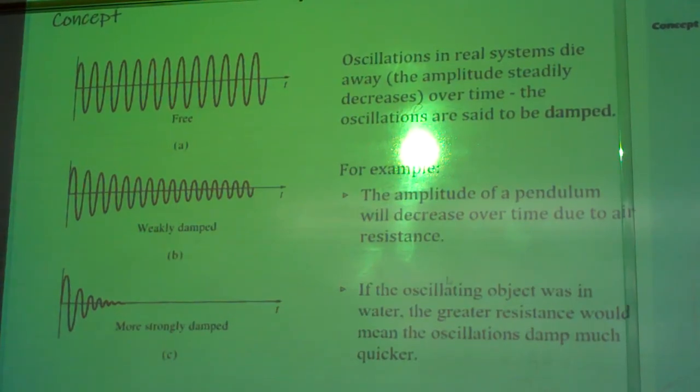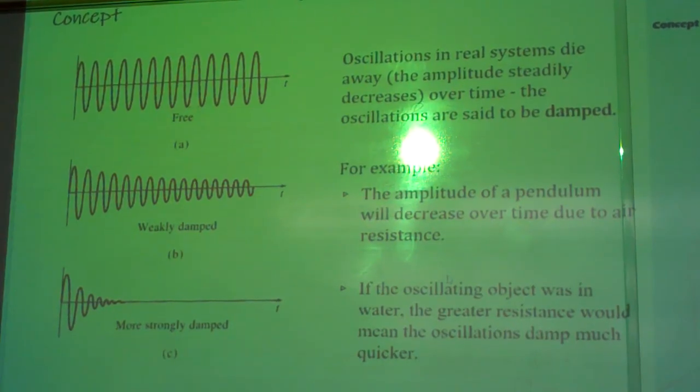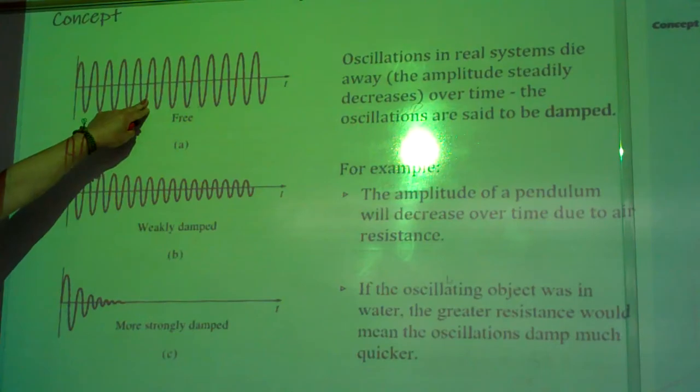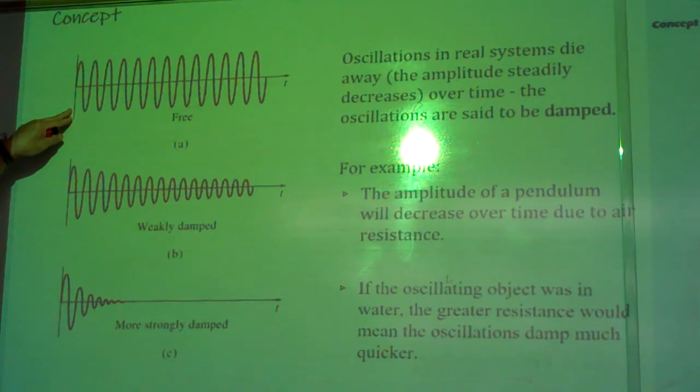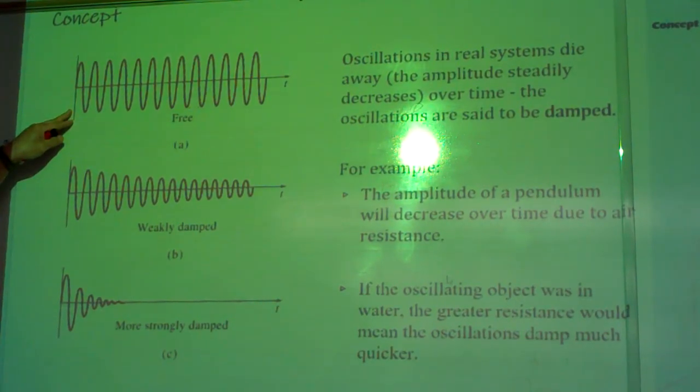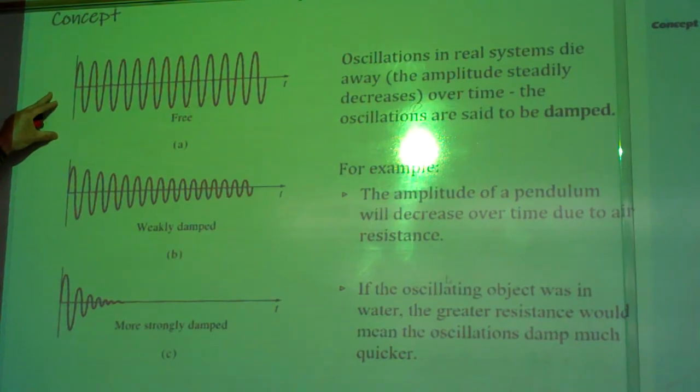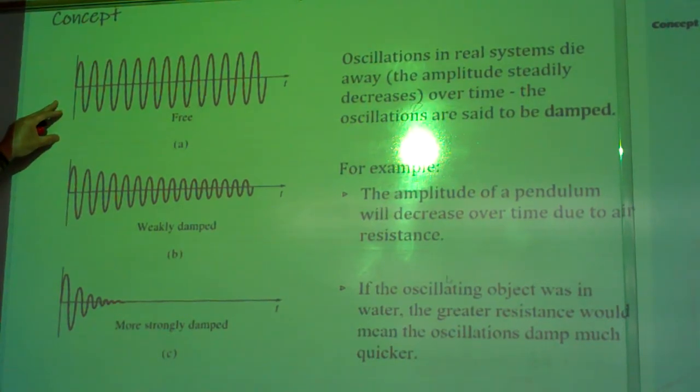Basically, here I'm showing you that if we solve for the system vibrations and plot them, the vibrations will be simple harmonic motion. You can see the amplitude is pretty much constant. This is undamped because there's no damping in the vibration process. No damping means the energy won't be dissipated. So from the beginning, the whole energy, including kinetic energy and potential energy, is conserved, and the amplitude stays constant.